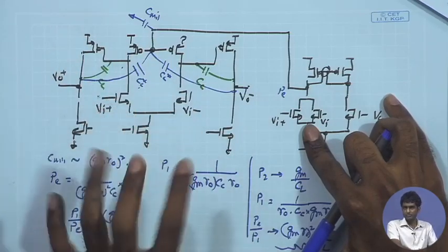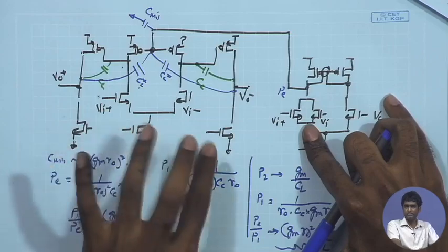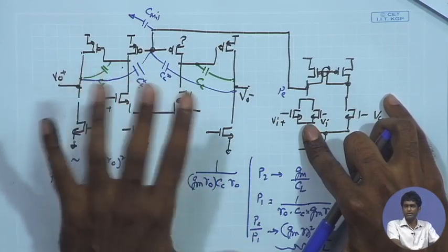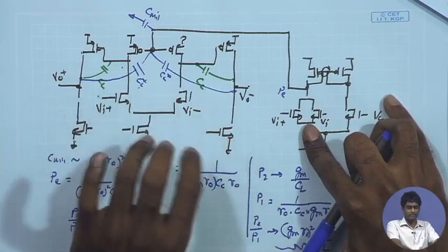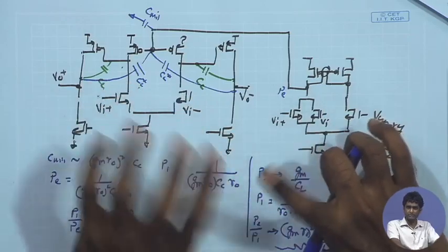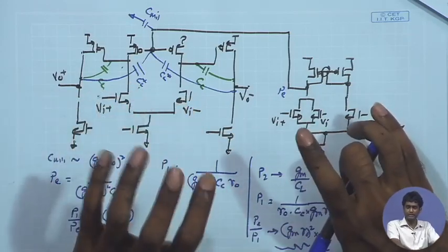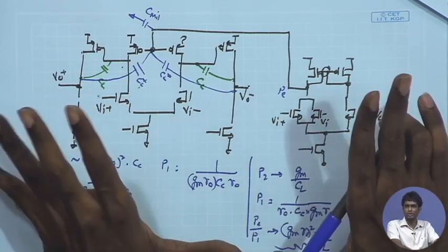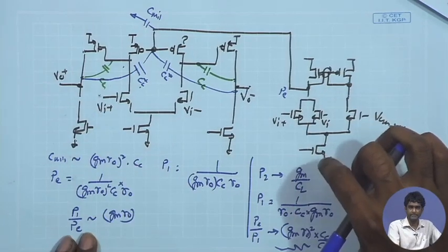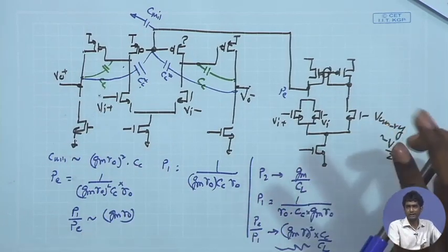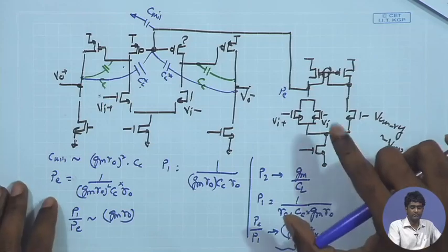So calculations can give you a starting point, and from that starting point you can do the simulations and tune the transistor dimensions or the component values in the right direction to approach the right specs. In general for calculations we will be using the second order model, which is not very accurate, of course.